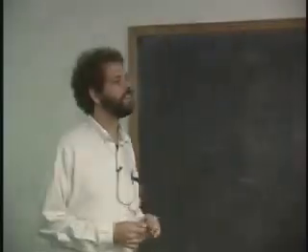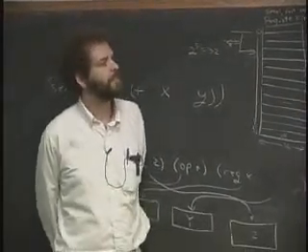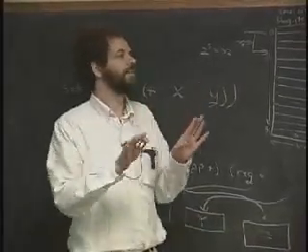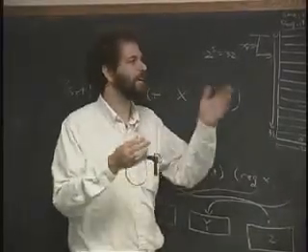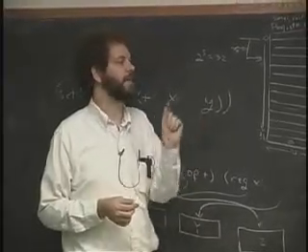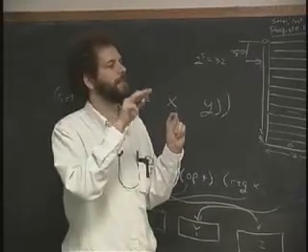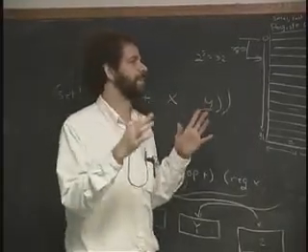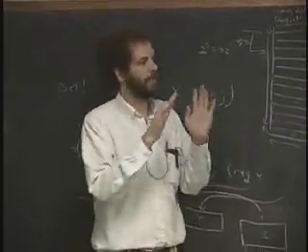In the real world example where you were saying you pointed to the bytes, does that mean that there's 4 times 32 bits worth of addresses? No, well, we aren't going to use the byte thing at all. In the real world, typically, if you're accessing the memory as data, you can get to the bytes. But if you're jumping to a particular place, you're forced to assume the last 2 bits of that place are both 0, so you have to go on a word boundary, or else the thing blows up. You get an error.